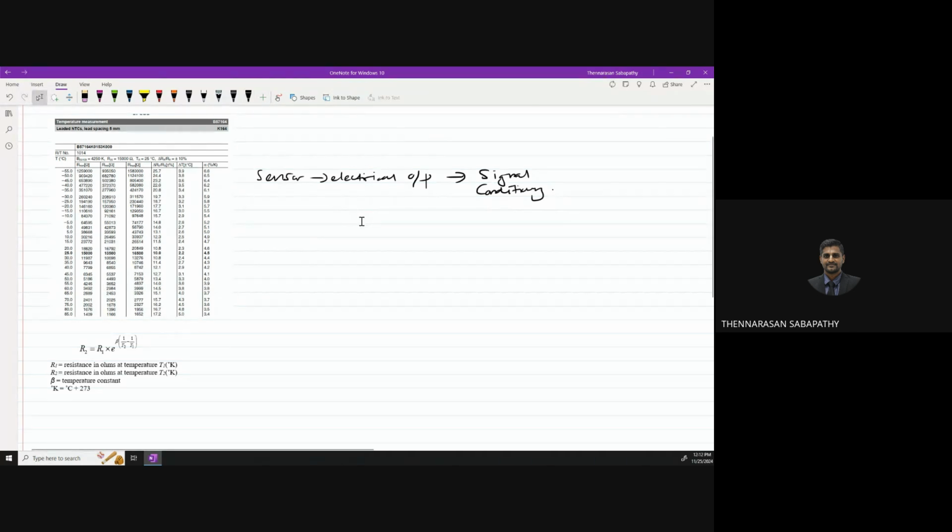But if the sensor reacts but doesn't produce an electrical output, only a resistance change, then you have to design it as a voltage divider or Wheatstone bridge.